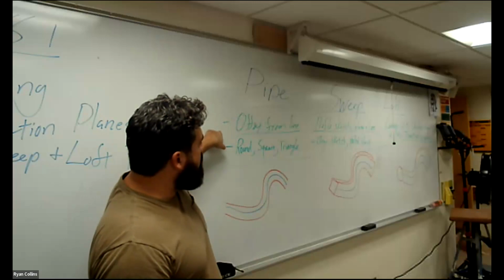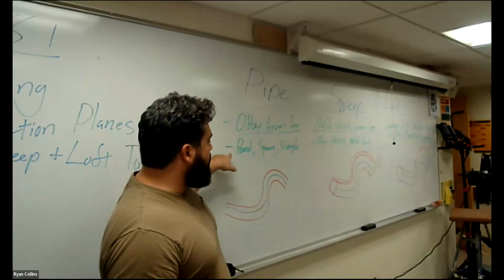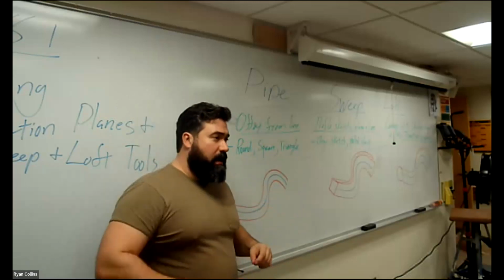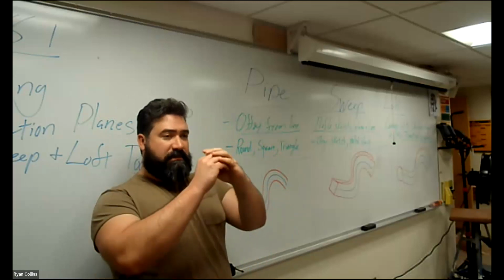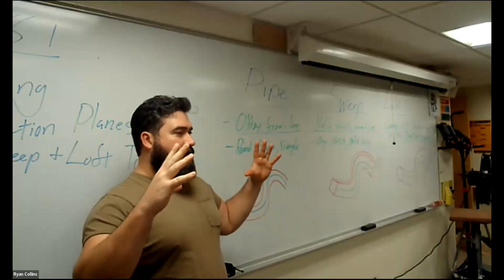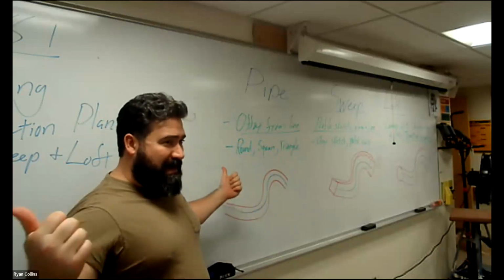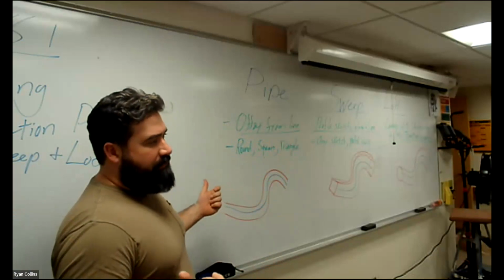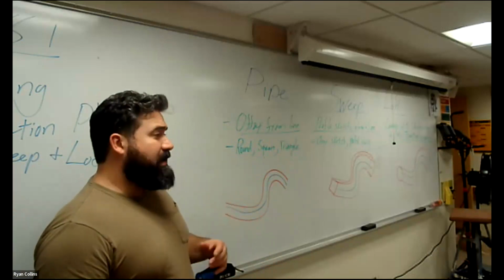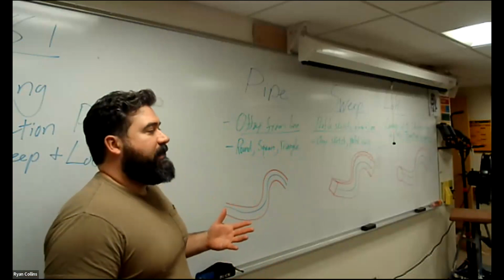We have a pipe tool. It is essentially a three-dimensional offset tool with a preset set of options. So you draw a line. A pipe tool literally makes a circle in three dimensions around that line. Now, it technically doesn't expand beyond the length of the original line, but if your original line is a circle, it's just going to build outward and make a donut around that shape.